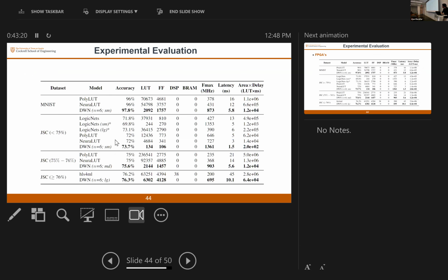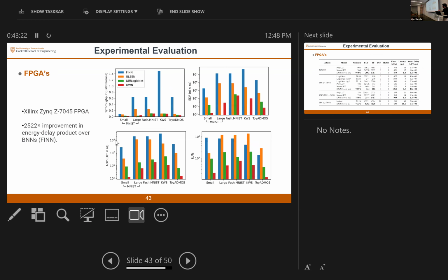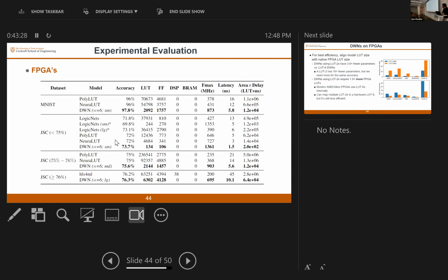And this here is just some graphs for you. The smaller the better in every case, we are red, FINN is in blue. And this one is comparing to LogicNets, NeuraLUT and PolyLUT, which is the one that gets a pre-trained DNN and converts it to lookup tables. And also you can see here, we have 100-fold improvements in area-delay products and everything compared to that, while matching networks.